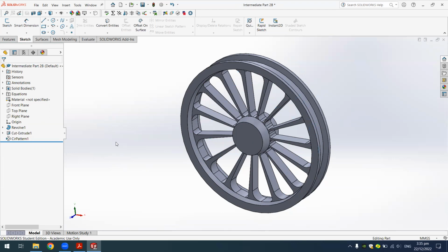If you circular pattern a sketch, some of the relationships and constraints such as concentric and same midpoint sometimes won't be duplicated, so your sketch won't be fully defined. And after duplicating it, it's a bit hard to make further changes.